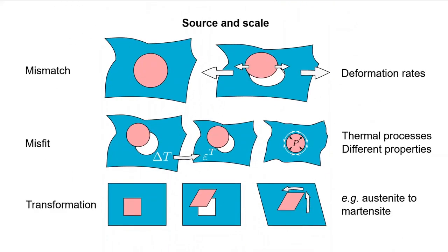As previously detailed, there are three main mechanisms by which residual stresses develop. Mismatch of deformation rates of regions within a component can cause them, as can a misfit. Material with different thermal expansion coefficients can result in different contraction rates during cooling, which can result in a region larger than the surrounding material can accommodate absent of stress. Finally, phase transformations can cause displacive stresses to form, exemplified by the martensitic transformation, which is shear-like, driven by a packing factor substantially changing between FCC to BCT structure.